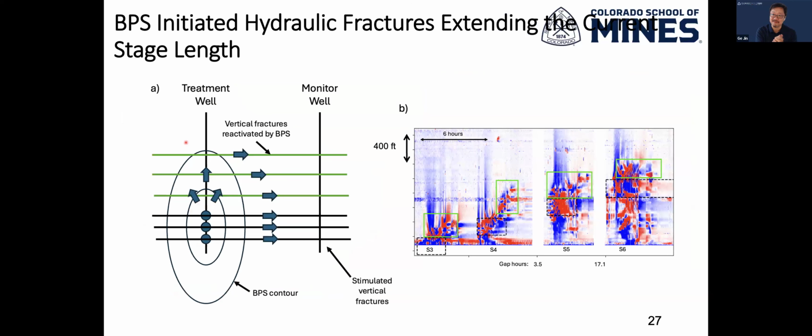So because this bedding plane has a much higher clay content and much lower friction coefficient, this could be the reason causing the bedding plane slippage. And if there is bedding plane slippage, it can explain all the phenomena that we observe in the data set.